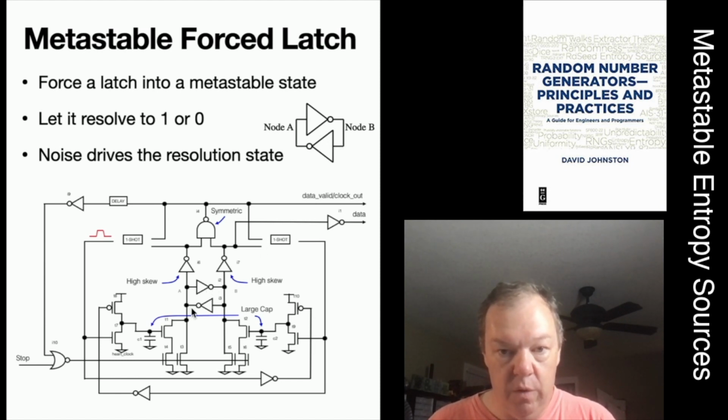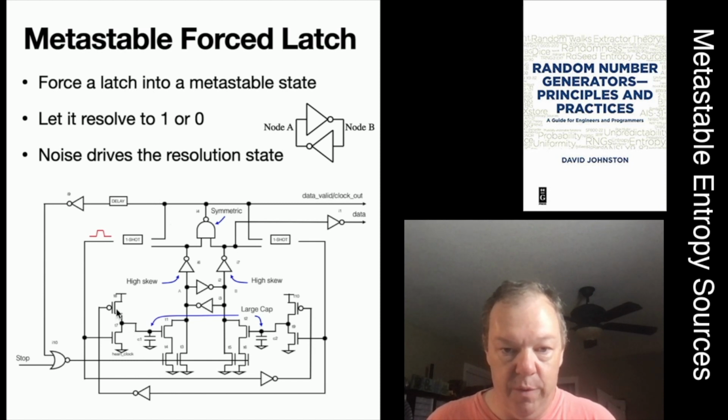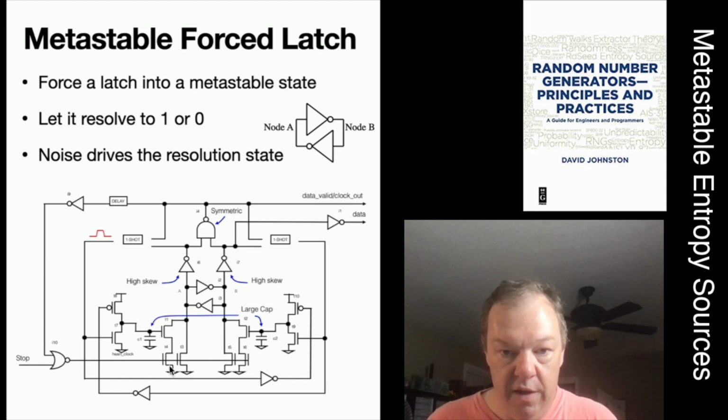So here in this circuit, we have this cross-coupled latch that is up here, but with a bunch of stuff around it. And this is what is implemented in the random number generator in Intel chips. This is kind of a cartoon version of it. For instance, if you were to dig into one of these transistors, you would find many transistors stacked, because these are supposed to be very weak. So we make them weaker by stacking them, so the resistance goes up. And down here are the honking big transistors, which pull it down. So when this line asserts, it pulls both sides of this cross-coupled latch down to close to 0 volts. And we see these two buffers. It sees 0, 0. And when you release it,